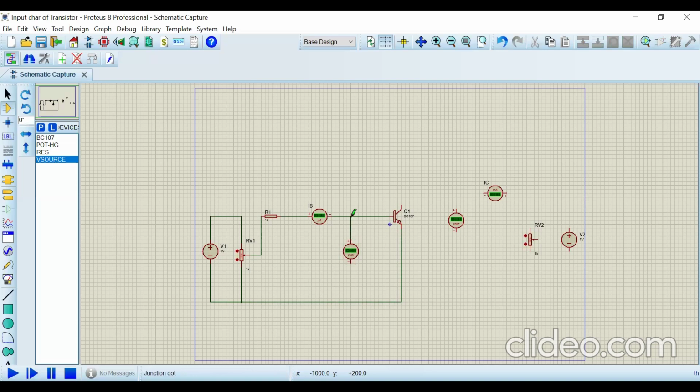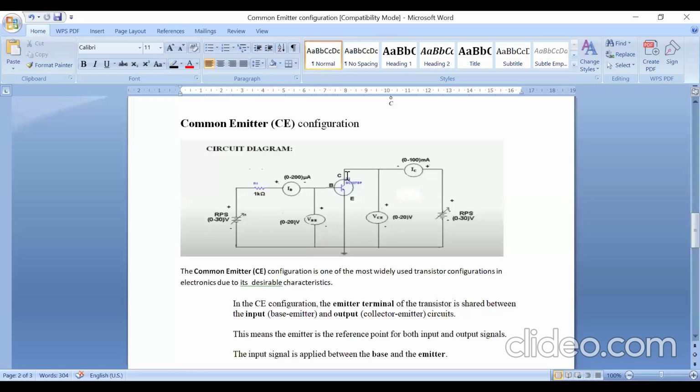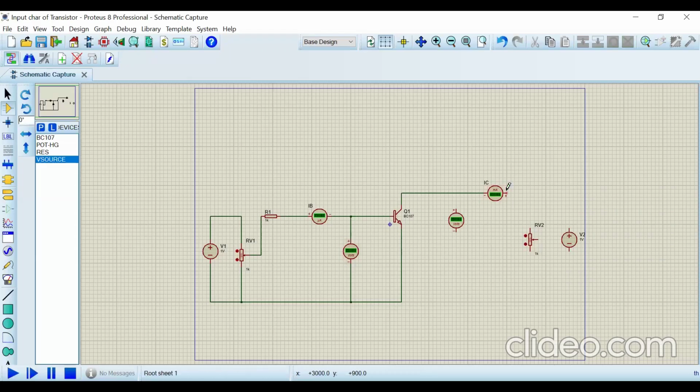And the voltmeter between base and ammeter, and collector should go to ammeter negative. You check here, collector is connected to ammeter negative, and this should be connected to the wiper. Okay, and this should be connected to the positive of the DC source, and the negative of the DC source should be connected to another terminal of the wiper potentiometer.